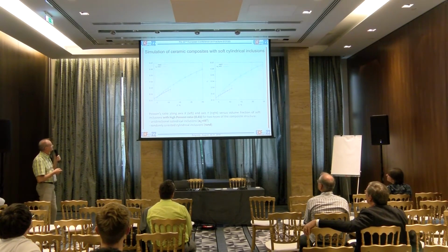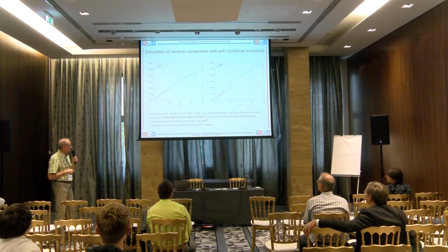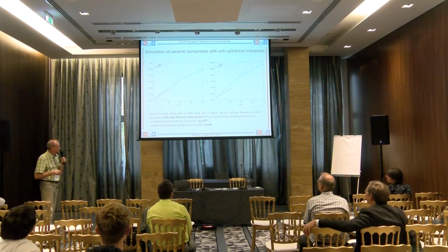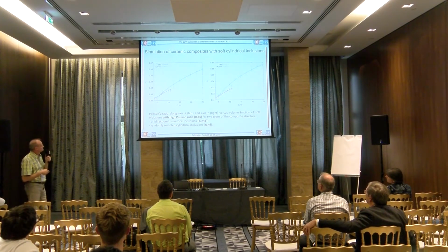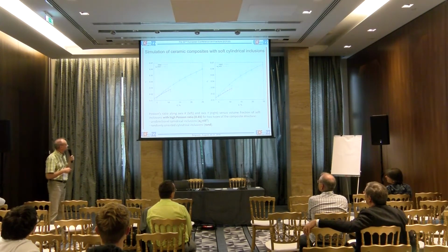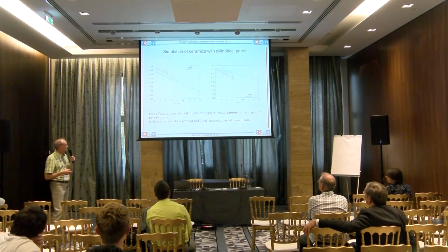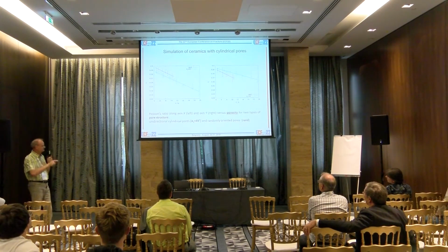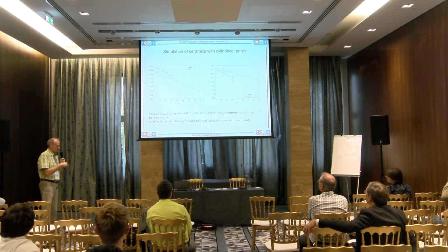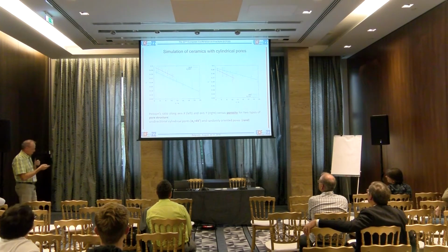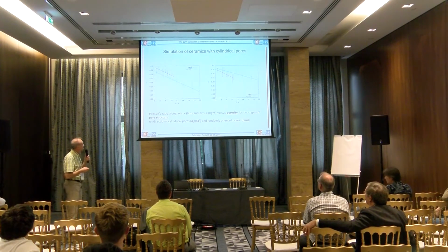But if we consider fillers with a larger Poisson ratio, before it was about 0.3, but here on this slide 0.45, it is pronouncedly increasing for both structures. And if we consider the same structure of pores, so with cylindrical pores, which actually means that there is no filler, and its Poisson ratio is actually 0, here it is pronouncedly decreasing for both structures.